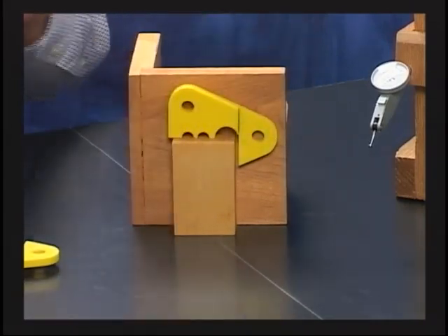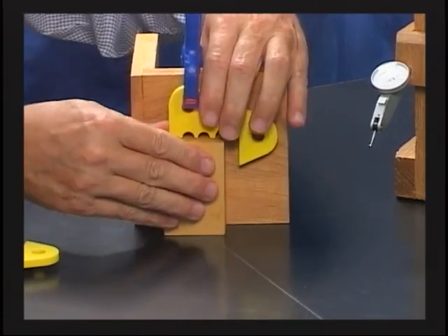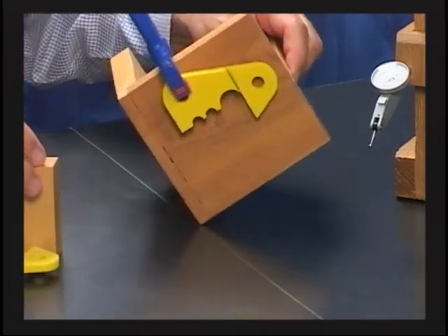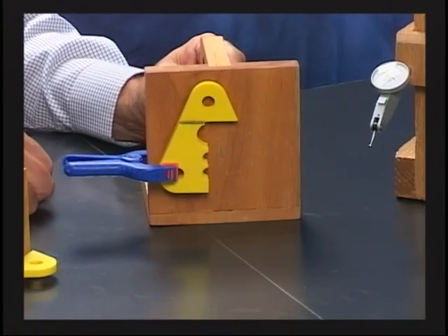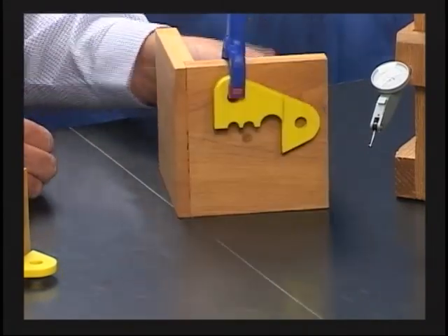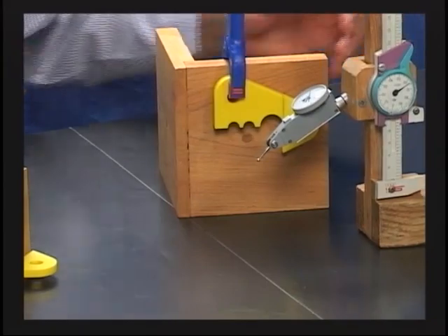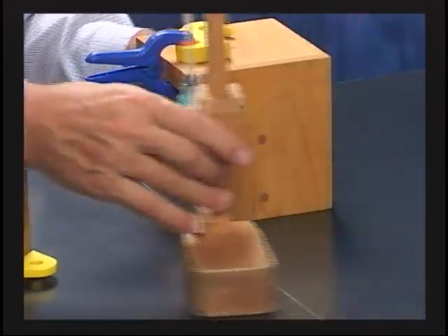And the reason I'll raise it up a little bit is so I can get a clamp on. And that's now lined up to my primary datum. Now once the thing is lined up to my secondary datum, you notice that when I'm going to make any measurements on here, that would be pretty straightforward. Making any measurements in this direction, you see I just take my height gauge. Well, first of all, I guess up and down, I could take all my measurements in this direction.